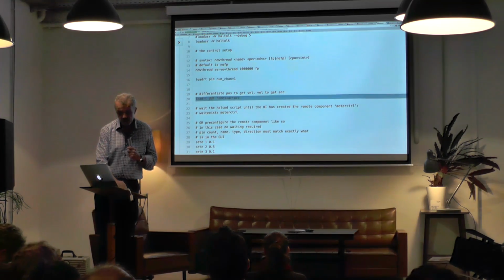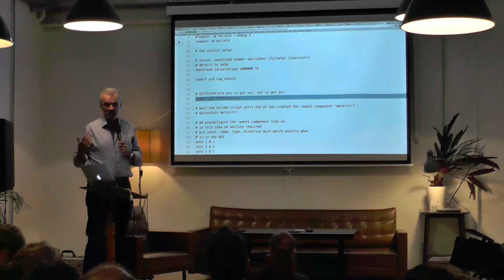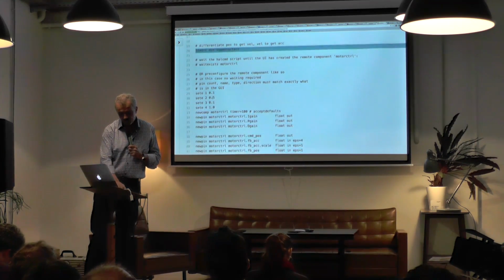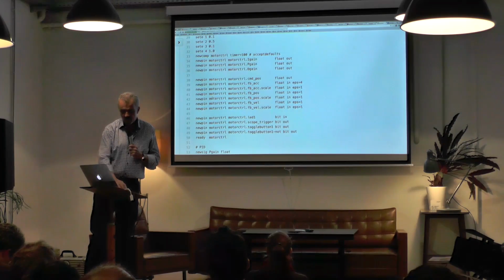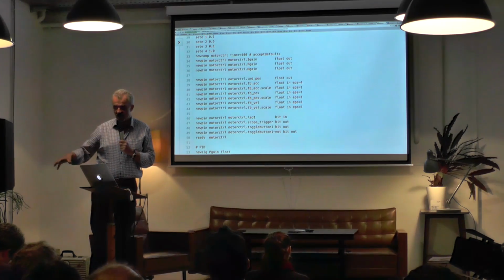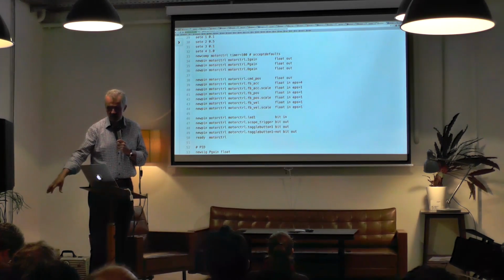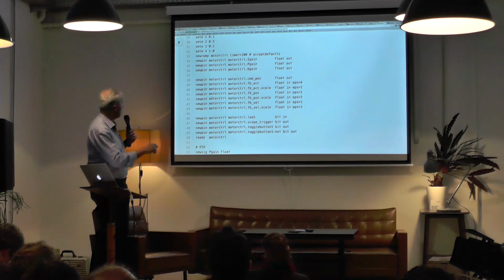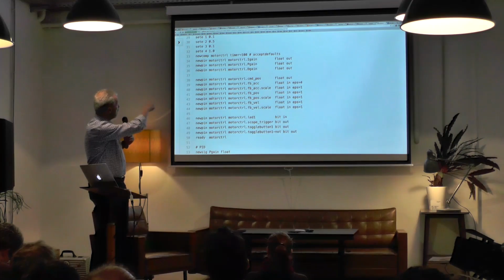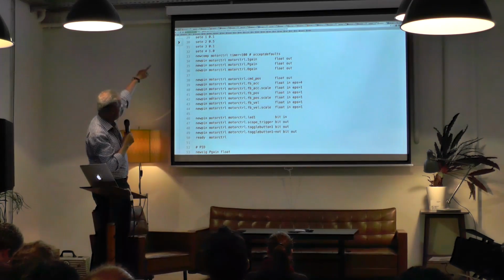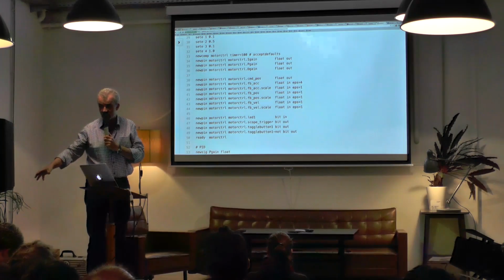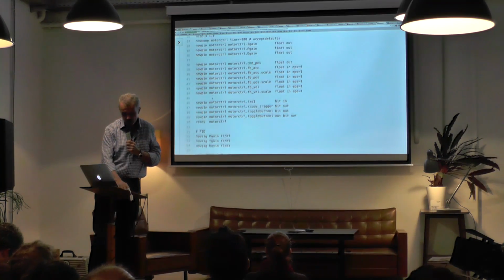We have the differentiators which do the acceleration and velocity estimation. We have the pro forma component which taps into the real-time part but really runs on the user interface. We call these the remote components. That's the definition, which starts with newcomp and has a couple of pins which corresponds to the user interface elements which are demonstrated.